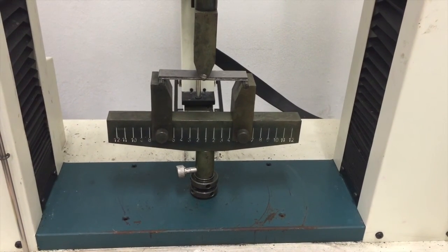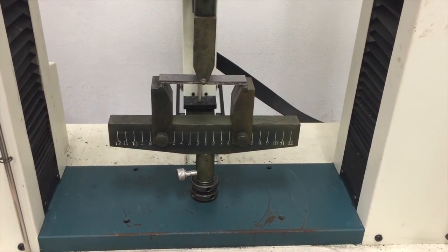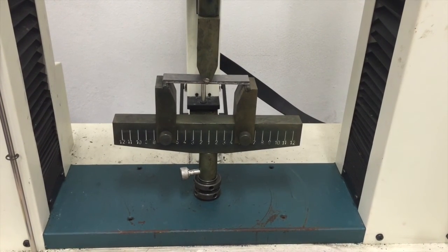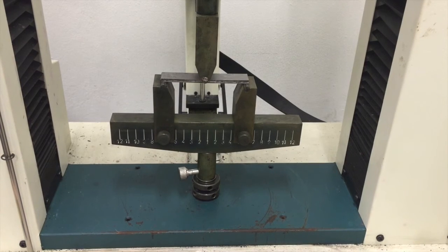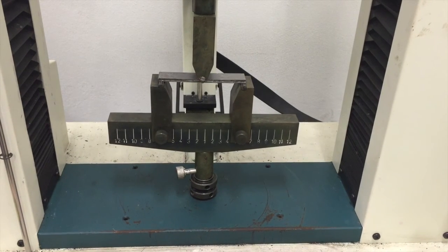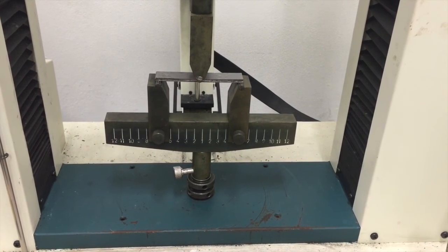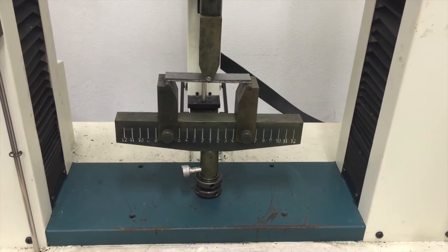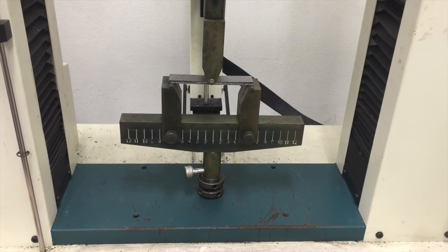First, our gluing process is handwork, so some locations on our beam are not as strong as we expected. Second, we could not control the proportion of the 2 glues, so the allowable shearing stress changed. Third, the beam bent while we were cutting, so it affected the gluing process.